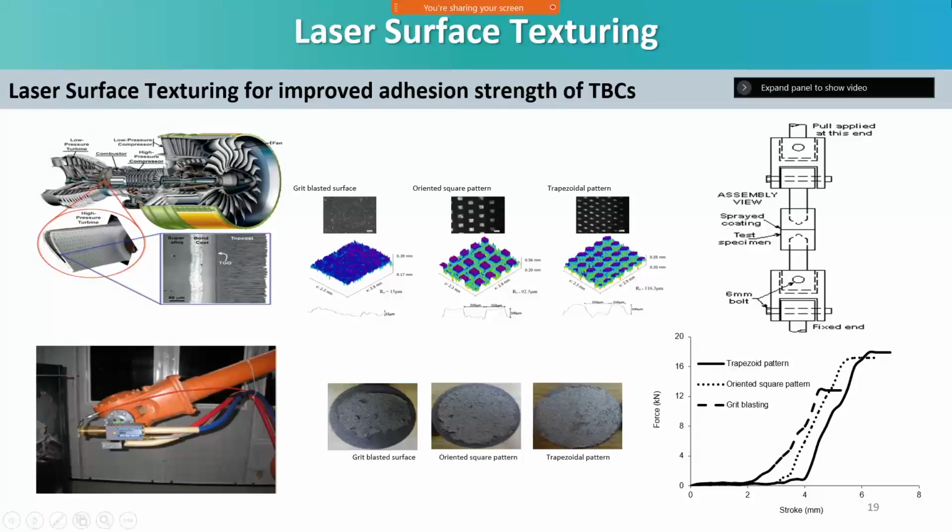It's not very visible, but you can see here it is around 15 micrometer, and this is 90 to 116 micrometers. So you can see the enormous increase in surface textured roughness, which provided a very good improvement in the capability of holding the TBCs for quite a long time, and from the serviceability part, improvement of service life, this is quite useful.